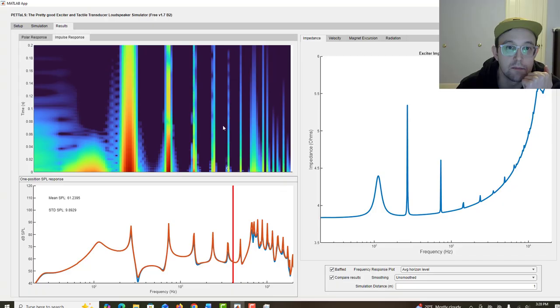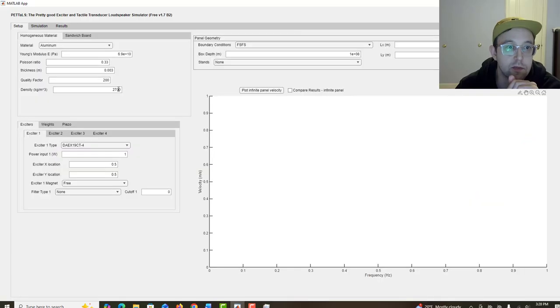So these vertical stripes in the impulse response are going to ring for longer because these peaks are sharper. If you rewind the video a little bit and look at the old ones, they probably aren't quite as bright for quite as long. So higher Q leads to sharper peaks and longer ringing in the impulse response. Let's compare that now to a really low Q.